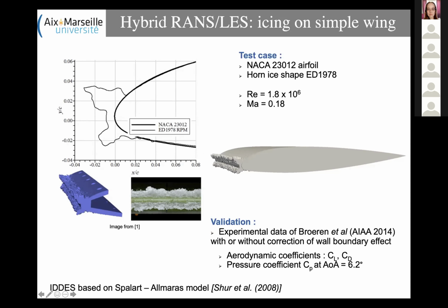And to do that, only an immersed boundary condition can be used because the geometry is so complex that defining a structured grid able to capture all details would be a nightmare. It's not impossible, it would be very, very complex. And on that, we run a hybrid RANS/LES simulation based on the DES by Spalart and his Russian colleagues, Strelets and colleagues.